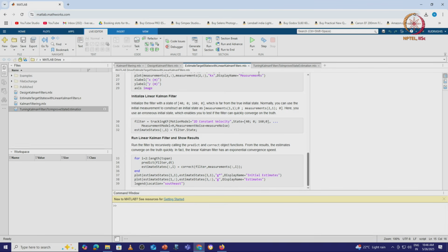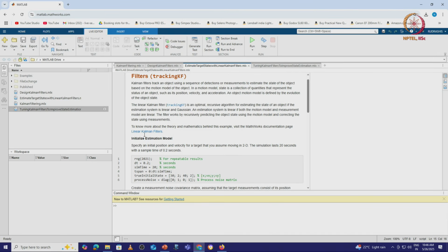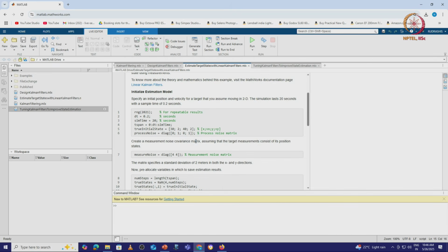get the estimate, right. So, you will be able to see you can do the 2D estimation, it is pretty straightforward once you know the linearization done for your nonlinear system, and if you have the A matrix, B matrix and C matrix, and if you have an idea about how your sensor noise is going to be, and you can initialize the respective P and Q, right, then we can get the filter done, okay.